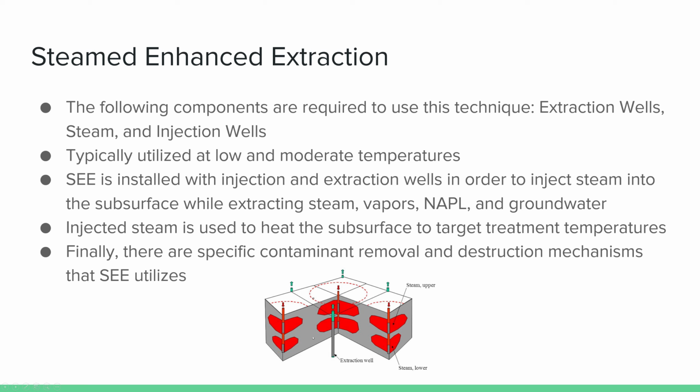In this example, the steam flow and zone are governed by a low K zone at about 5 to 6 meters in depth. Also, when using this technique, it is important to remember and consider that the monitoring and adjustments during heat up are important and expensive as well.